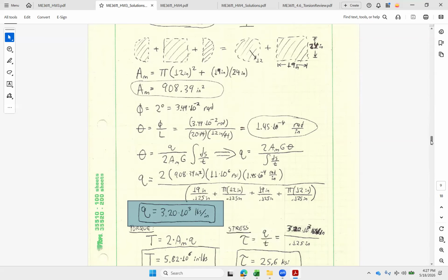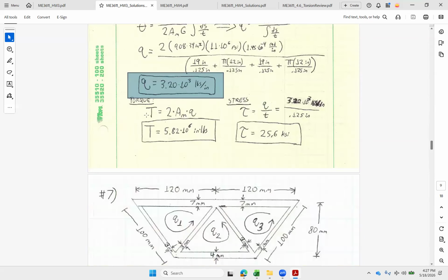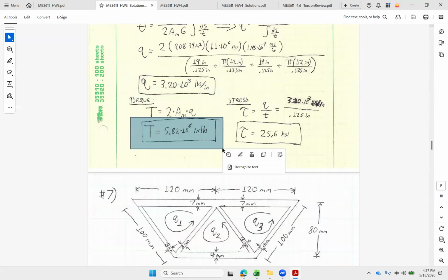Once we have installed it, and remember, we're not going to find a giant wrench. We don't have a wrench that's long enough with a long enough moment arm to be pulling with 6 million inch-pounds, right? No matter who we call, even if we called Andre the Giant and got a 100-foot-long pipe plugged into the end of the torque wrench, we're not going to get this number that we need. So we're going to have to get it by putting the bolts in kind of loose and then torquing them down individually until it forces it over.